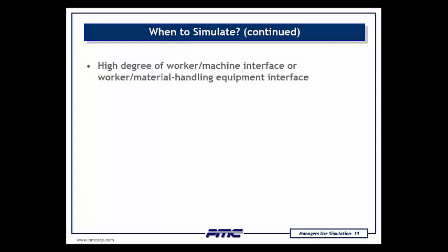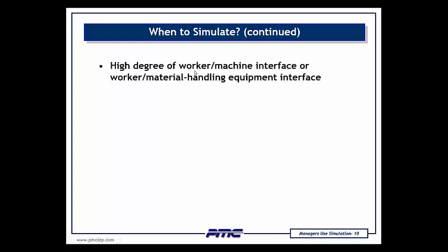And same header. This comes up very often. For example, the first half of this bullet point, you may have semi-automatic machines, by which I mean a worker sets it up, puts the part on, presses a button, the machine cycles automatically. The worker, if you design the process well, can then go off and productively do something else, but not too far away, and then come back to do a tear down, take the part off the machine, check the quality of machining, check the machine, etc.